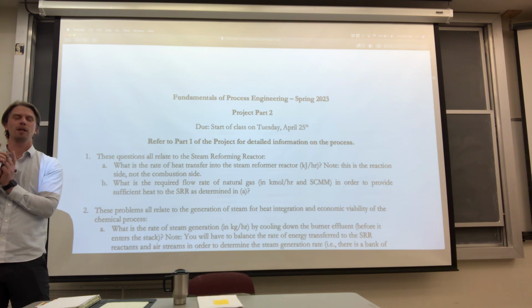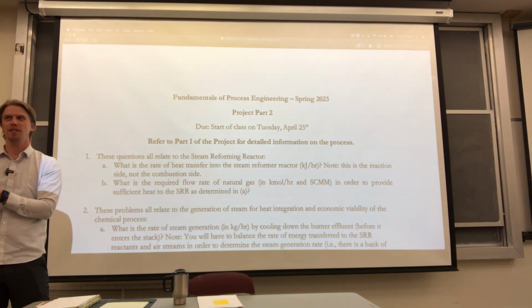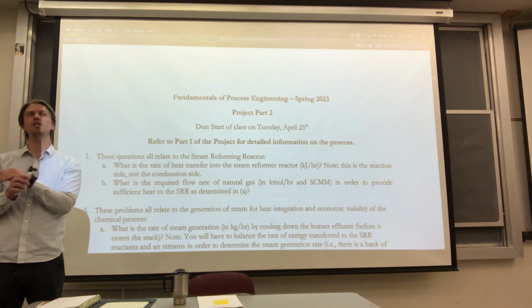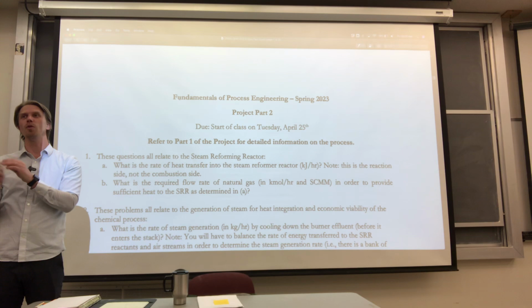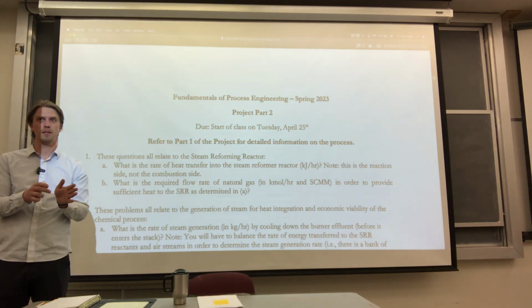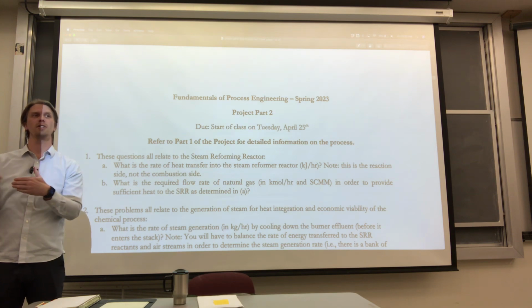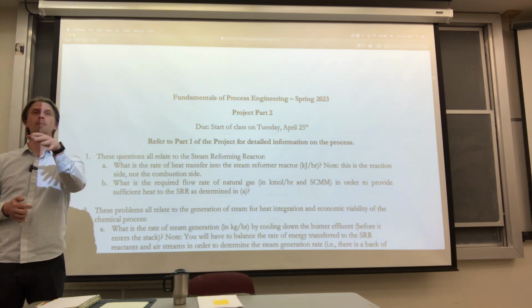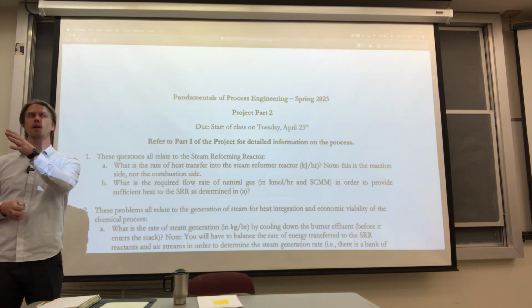Not everyone, but a lot of people did 25 to 65, because 25 is sort of the standard state. What we needed to do was to go from the outlet conditions of 60 to the boiling point. That's how you get the heat of vaporization at that particular point. Or rather, you go from the normal boiling point to 65 and then integrate it back.